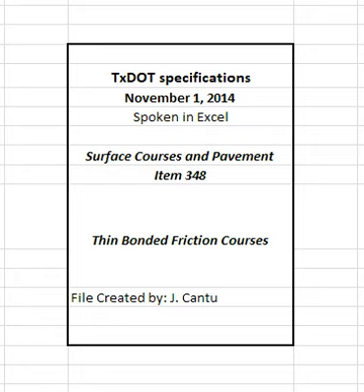4.3.5 Placement and compaction. For placement and compaction, include proposed agenda for mandatory pre-paving meeting, including date and location. Proposed paving plan, for example paving widths, joint offsets, and lift thicknesses. Type and application method for release agents in the paver and unrollers, shovels, lutes, and other utensils.